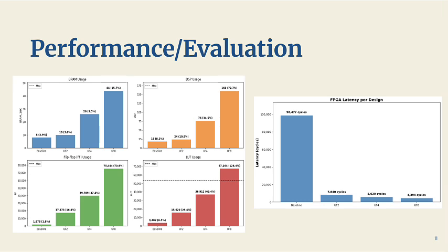The baseline design takes 98,477 cycles, whereas with an unroll factor of 8 the design completes in about 4,394 cycles, a decrease in latency by a factor of 22.41. Our target devices are the Z boards that were utilized throughout the HLS course, and ultimately we could see that by using an unroll factor of 8, it utilizes more LUTs than accessible, exceeding the limit by approximately 27%. In turn, our final design uses the unroll factor of 8, resulting in a latency reduction by about 17.52 times.